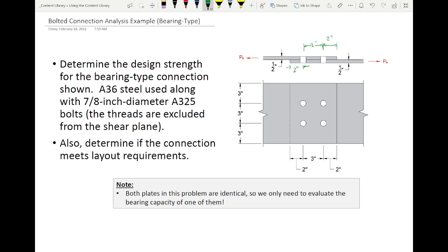Does that make sense? So what you're seeing here, see why this is a solid line and this is a dashed line? Because you're looking on top of the plate, so you can see this plate edge, but this is like the plate edge underneath that would be there if you had X-ray vision. Does that make sense? That's a really good question.